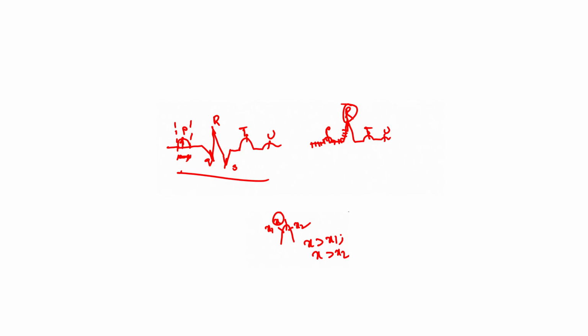So I have to know some knowledge on the QRS peak too, some knowledge on the ECG signal too. If we recall what the professor said in the class, we understood that the QRS amplitude peak is comparatively very large when compared to the other peaks in the ECG signal. So if I put some threshold, that means out of the complete ECG signal, what is the maximum peak that I am getting? On that maximum peak, I will fix some threshold somewhere around 70%, somewhere around 50% of the peak. So like say this threshold, it will allow only the R peaks to pass through, and whichever peaks are below the threshold it will not allow.